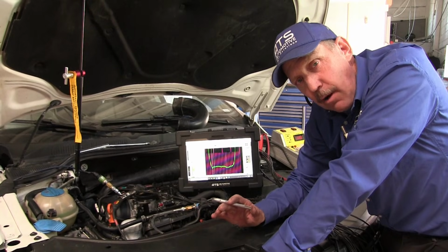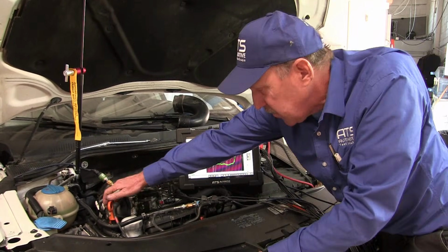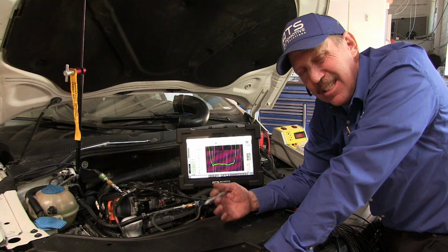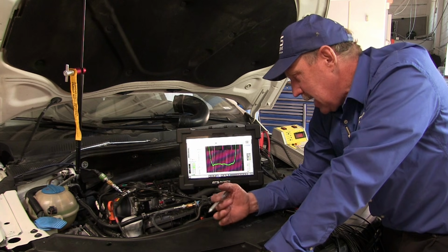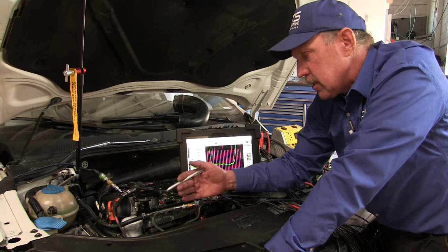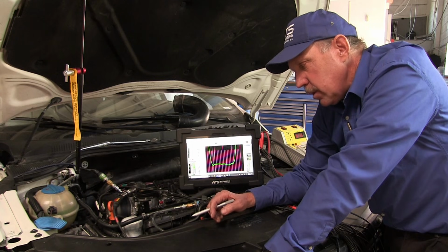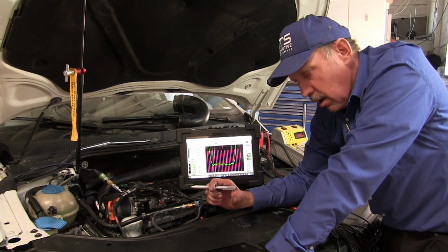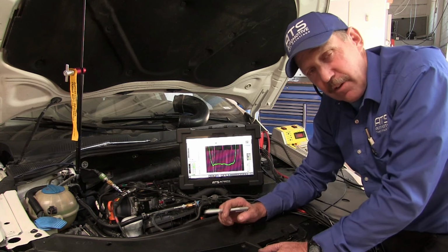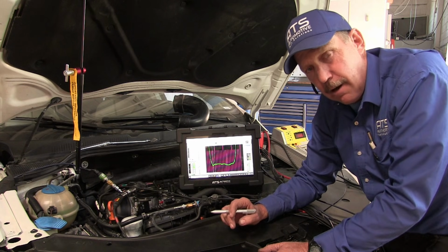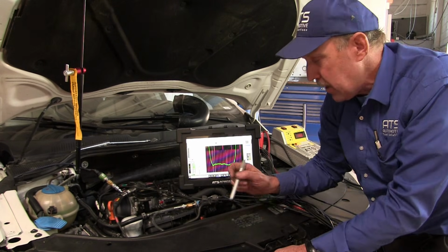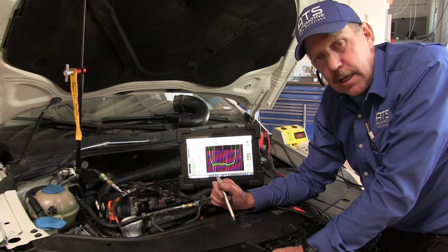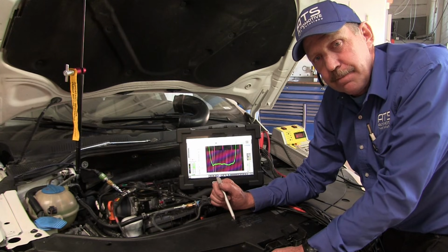So now my belief is that this phaser has the problem, that it has moved the intake cam significantly. And if the intake cam moves, then it's going to have this problem. So I want to pop the phaser out and look at it. When these come apart, the valve assembly, these are very complicated spool type valves, and they break and come out and allow full oil pressure to move the system. So let's go ahead and get that valve out and take a look at it.